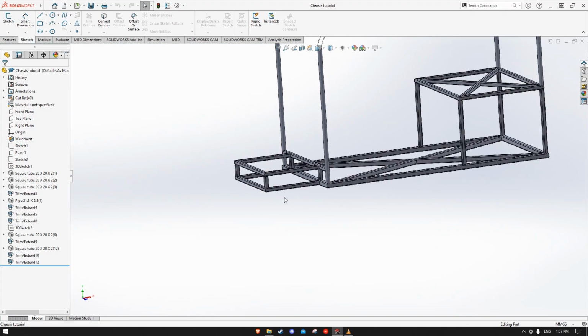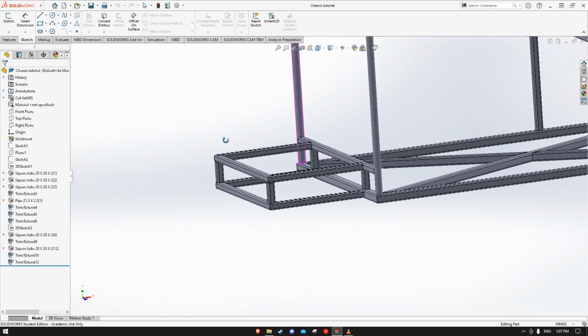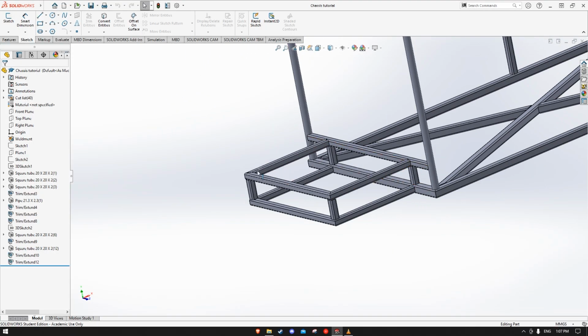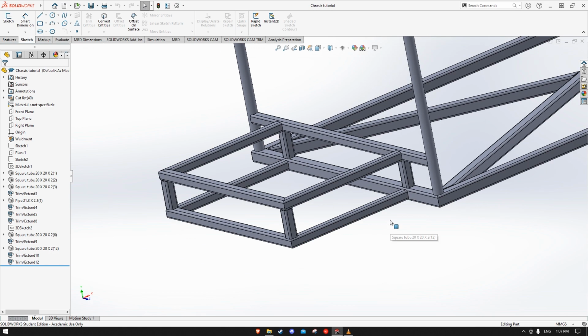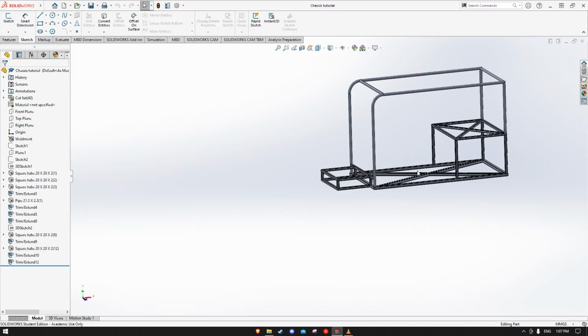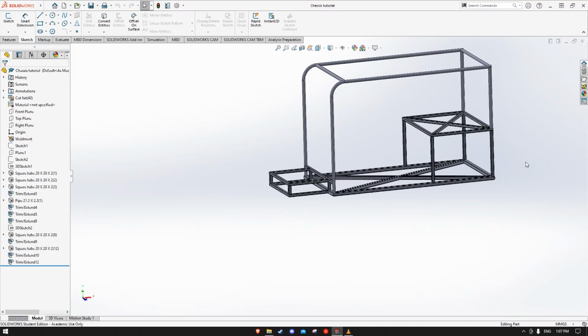Second thing is you have to draw the suspension mount, which you have got from assignment 1. I have just assumed a rectangular shape here. The arms are going to go here and here on each side, here and here for the double wishbone. So the next step is to have an idea where your components are going to be placed.